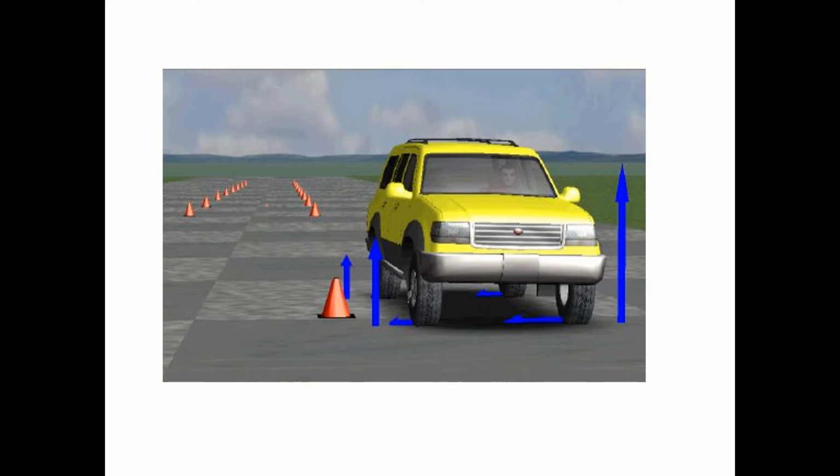So you can see here, when the vehicle is taking a turn like this, you will get the vertical force here. You know, this is the inner side, there is the outer side. The load on the outer wheel is high, that's why you can see this vector is quite long and this vector is small compared to this because of less load, and you will get the side force.